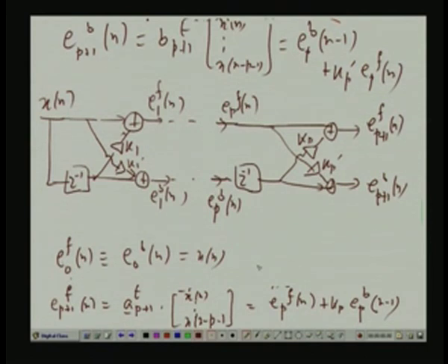This is one of the most celebrated things in statistical signal processing. This is used for AR modeling and is particularly used in the speech context, because our speech generation mechanism in our vocal cord has been modeled as some kind of AR model, which is driven by some white sequence. Only thing, the AR model parameters get changed from time to time, and you produce various sounds.